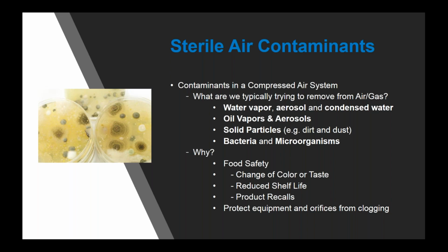When this water and the compressor oil mix, they can form a pretty nasty emulsion that's really a great breeding ground for microorganisms. So they'll sit there at that interface between the water and oil, and they will drink the water and eat the oil, basically. It's a great growth environment for them. So as a reminder, these contaminants are all dangerous to food quality and consumer safety and really need to be treated as hazards when that air contacts the food or the food packaging surfaces.